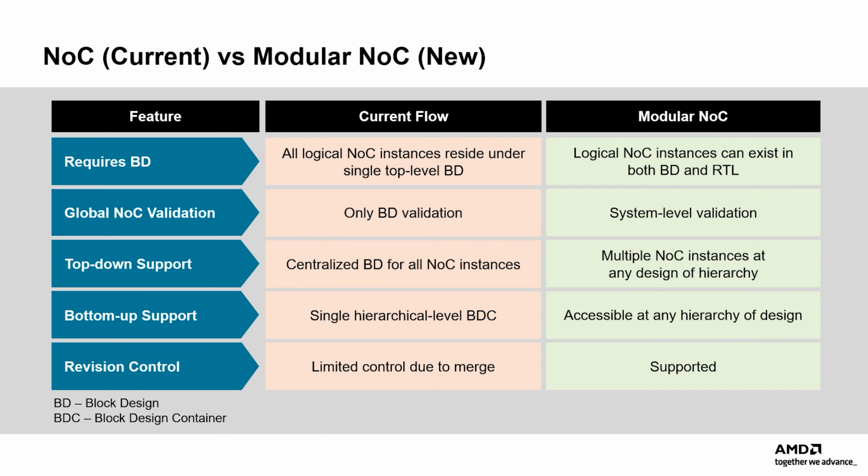Now that we have walked through the steps of using a modular NOC and reviewed its supported use cases, let's see how it compares with using the IP integrator only. For both flows, the BD is required, but with the modular NOC flow, the BD can be instantiated with the minimum required IP, such as the SIPs and DDR memory controllers. In the current flow, NOC validation is only possible within the BD, but now with a modular NOC, users can validate the NOC at the system level.